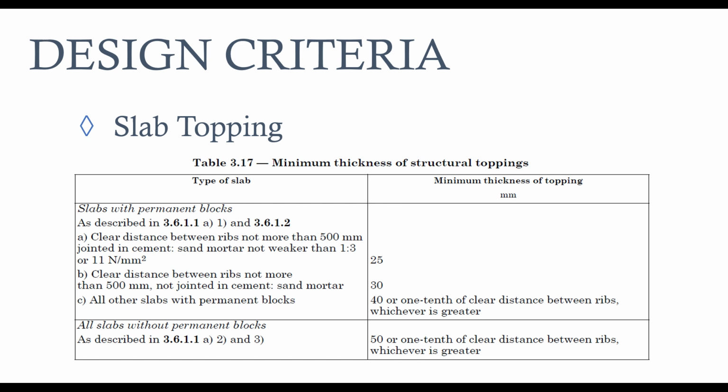One way of understanding this is in the case of asphalt on a bridge. You know, the asphalt is not really contributing anything to the strength, so it's referred to as a superimposed dead load. That is a dead load, but it is not contributing to the strength of the structure. So this also applies in a rib slab. So whenever you have your slab topping not contributing to the strength, then you have to consider what is the minimum thickness you can use.